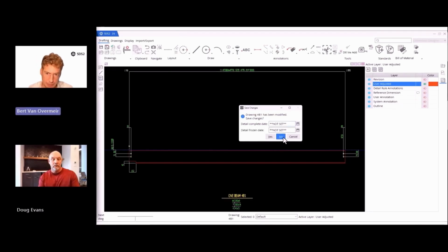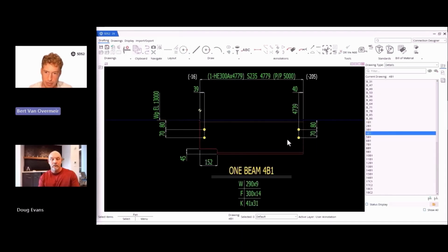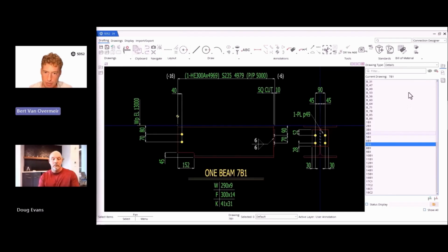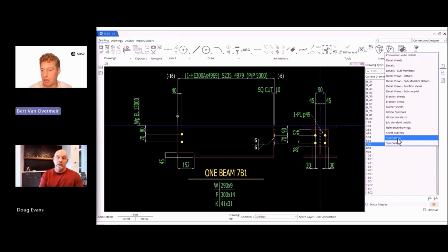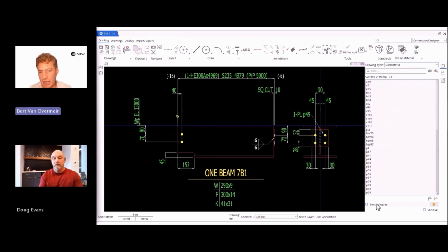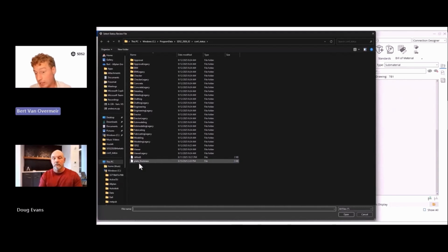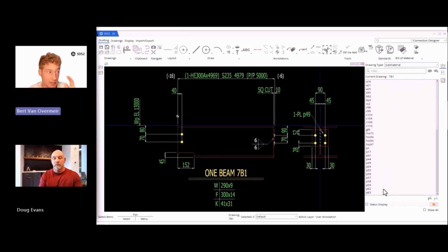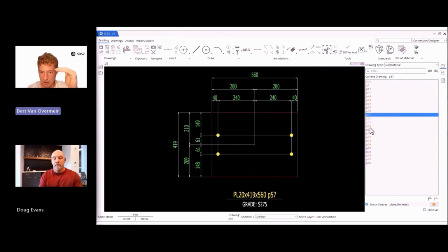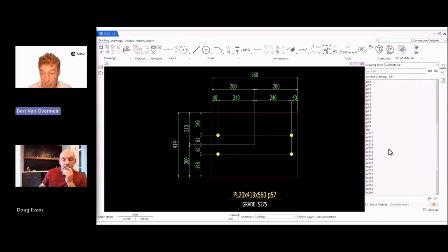Not only that, but we've also worked on status display. If you remember, status display would allow you to filter between different entries to see a part of the drawings that you needed. I've created an example here, and you will immediately see what changed. If we filter for plate thickness in these submaterials, you can immediately see that they are now colored per plate thickness. I've added some coloring before, and they are now categorized per color. So you can easily see what plates you actually need, which submaterials you actually need to edit or do something with. That's quite an improvement, if you ask me.